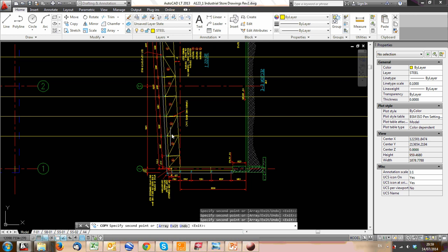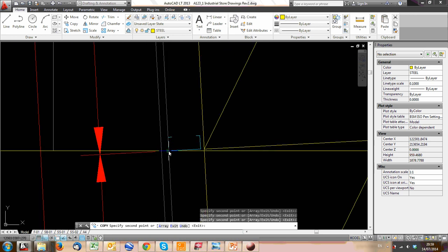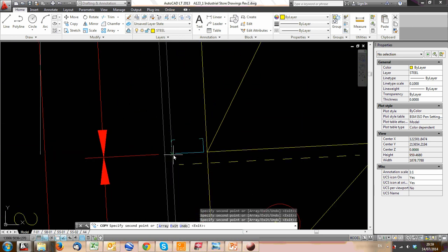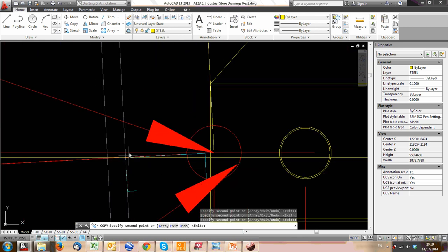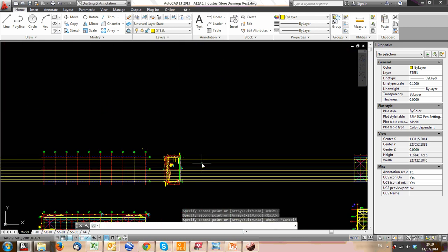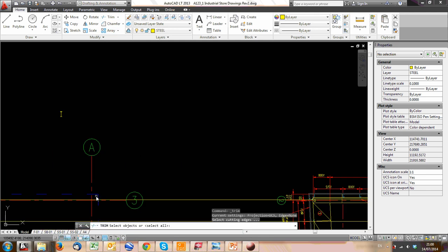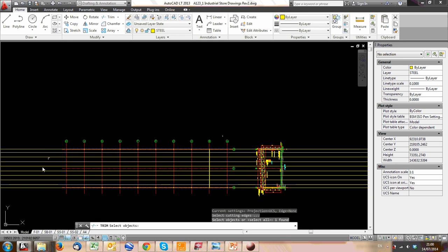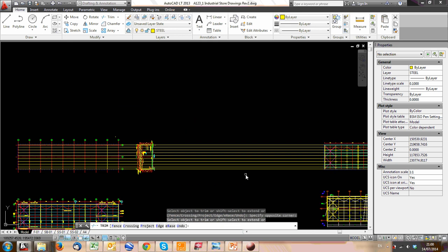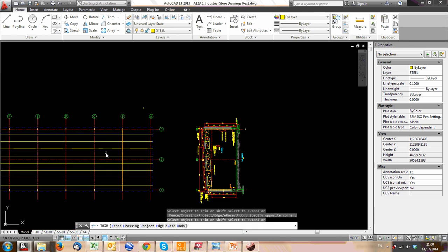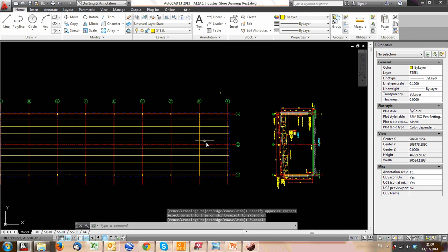And this applies, you can use this sort of projecting tool for many different things. Often, once you've done one layout, you put it next to another and then project from it to create all the rest of your drawings. Alright, now that I've got all those in, I'm going to click on trim, click on the edge of that, so that's going to be my trim line, press enter, select all of those, and it's trimmed it. Alright, so now we have all our purlins in place.